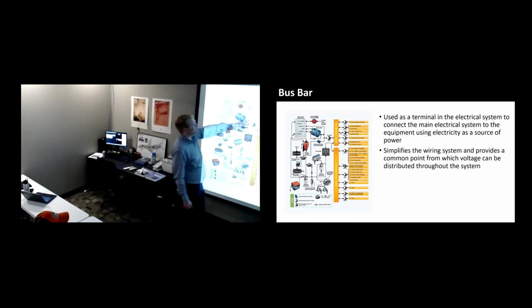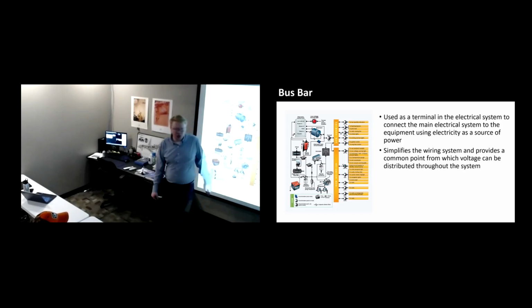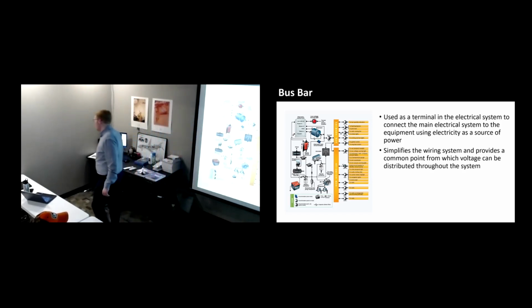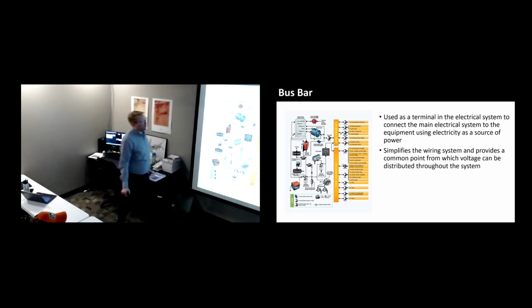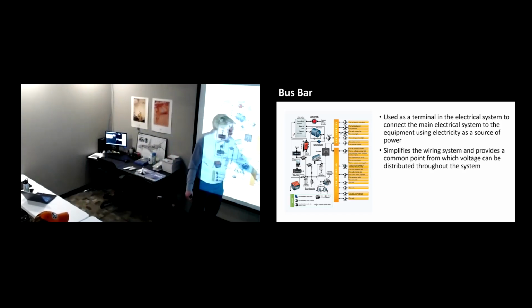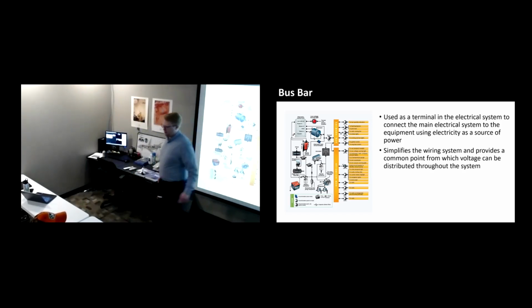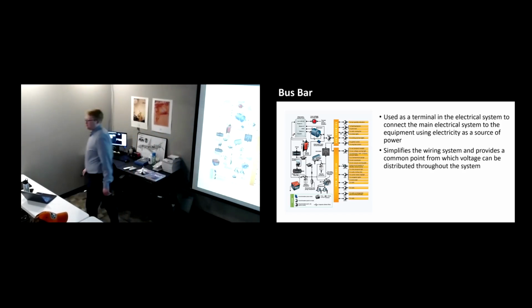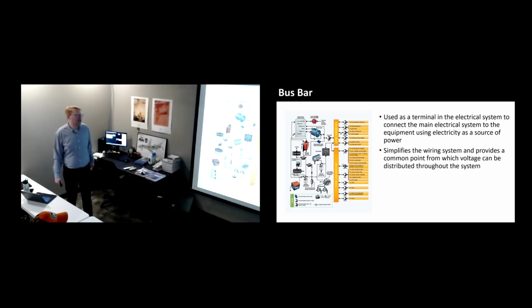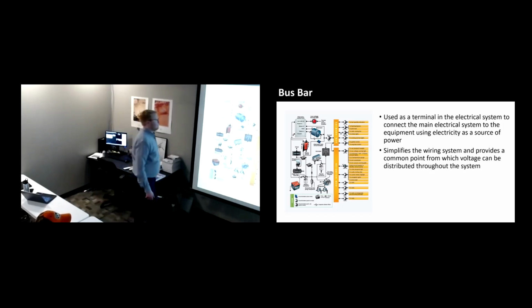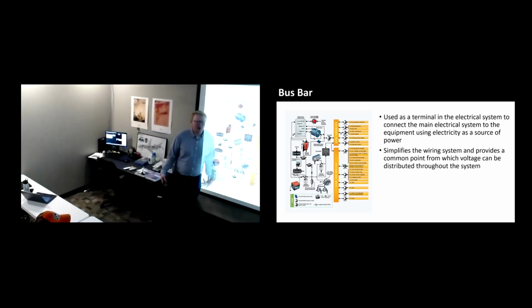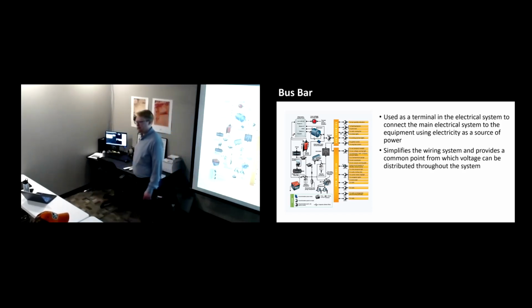For example, a primary bus may have things like a wing flap, if you have an electrical wing flap, landing lights, strobe lights, a flashing beacon, or fuel quantity indicators. Those are what we would see on a normal primary bus. Whereas an avionics bus may have things like autopilot, navigation radios, communication radio, those kinds of things. They would be connected to an avionics bus bar. Questions on bus bars? They're a way of delivering voltage from one space to another.